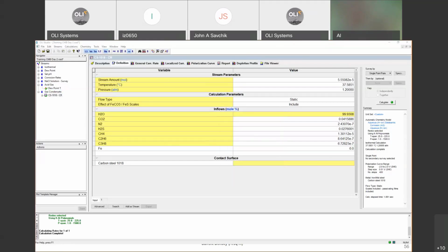The third question is, did you find where the repassivation potential is in the polarization curve? I went to our CTO to ask this question. Currently, in the polarization curve, we don't show the repassivation potential. There is not an option. That's a request that I made just yesterday, so that we can add the repassivation potential on the polarization curve. An approximation of that repassivation potential will be where the peak current density crosses the anodic branch of the polarization curve. I'll talk about that later in the presentation.